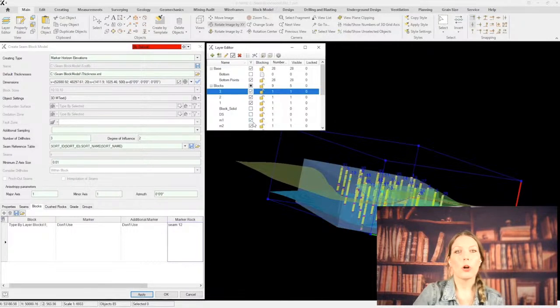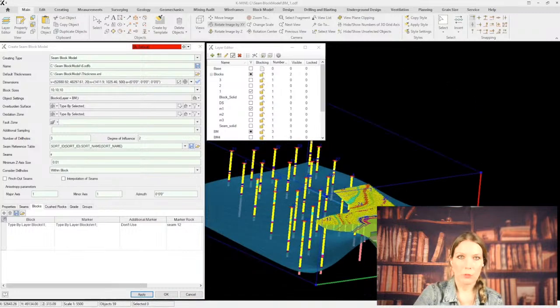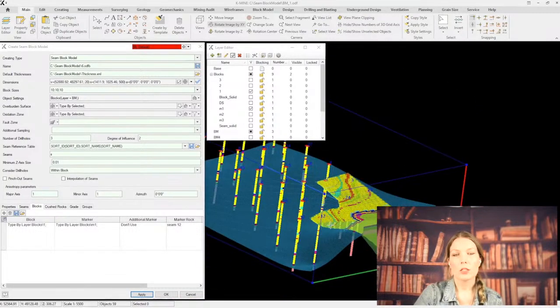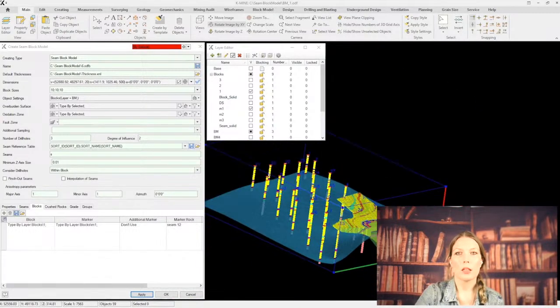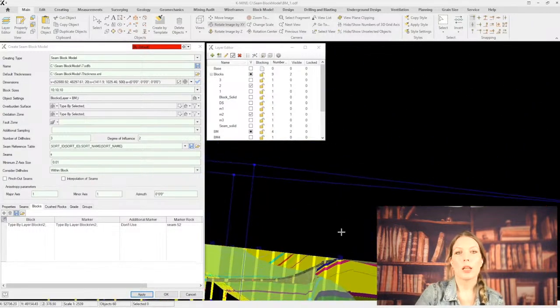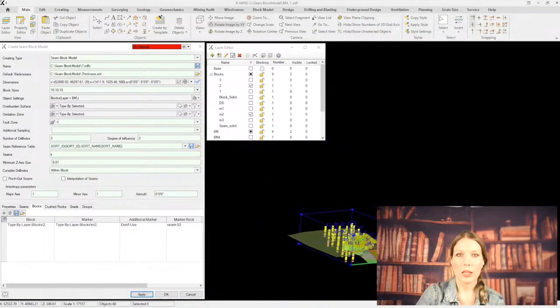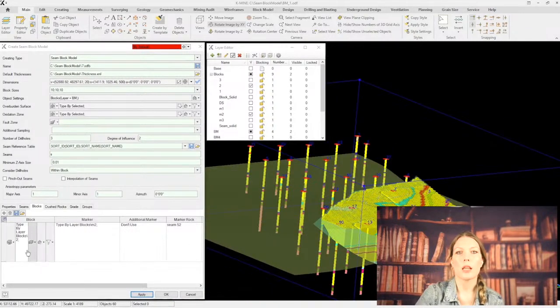In the presence of faults, upthrust, and displacement, a marker surface must be created separately for each tectonic block. The solids of these blocks are then used as constraints before interpolating the layers across the entire model. This approach allows the model to accurately reflect significant displacements, amplitudes in the layer position, and thickness at fault boundaries.